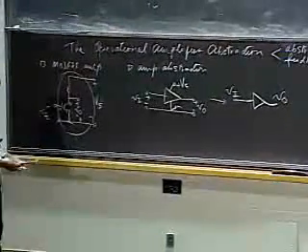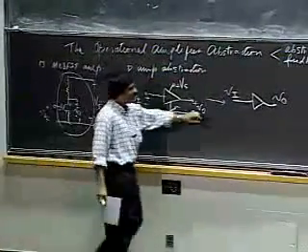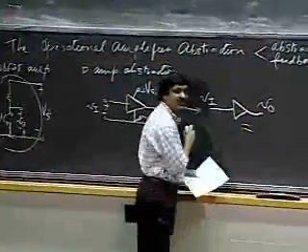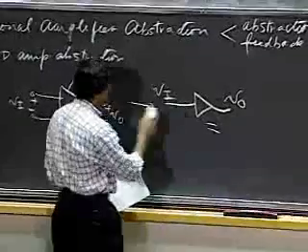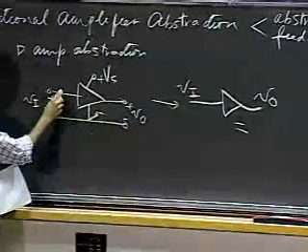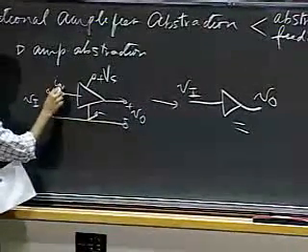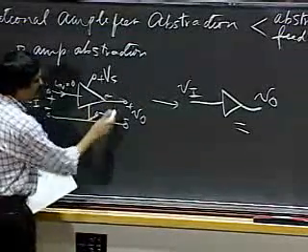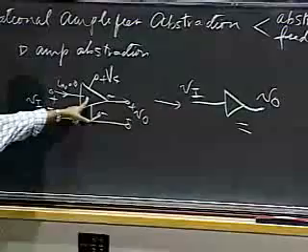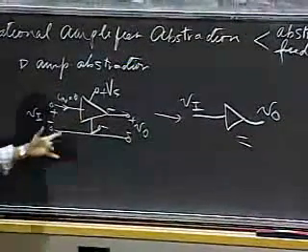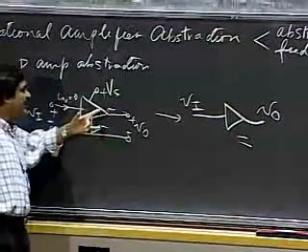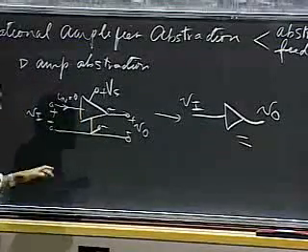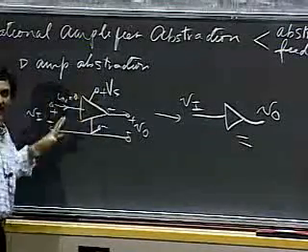So what we can do is, provided we know, we can abstract out the relevant properties of this block and expose them outside. And the relevant properties might well be that, let's say here, the properties may be that I in is always 0, right? I can also express to you the gain of this amplifier. I may also be able to tell you a Thevenin equivalent for the output. Okay, so there are some properties that I can give you that will let you use this building block abstractly.